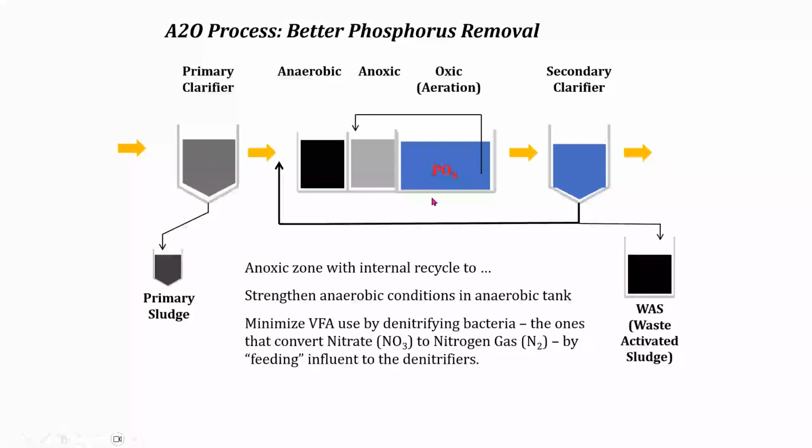They haven't grown. And in the aeration tank, the energized bio-P bugs, phosphorus removing organisms, multiply, and as they do, they pull the phosphorus out of solution that they released, as well as the phosphorus that was in the influent and passes through these two tanks.